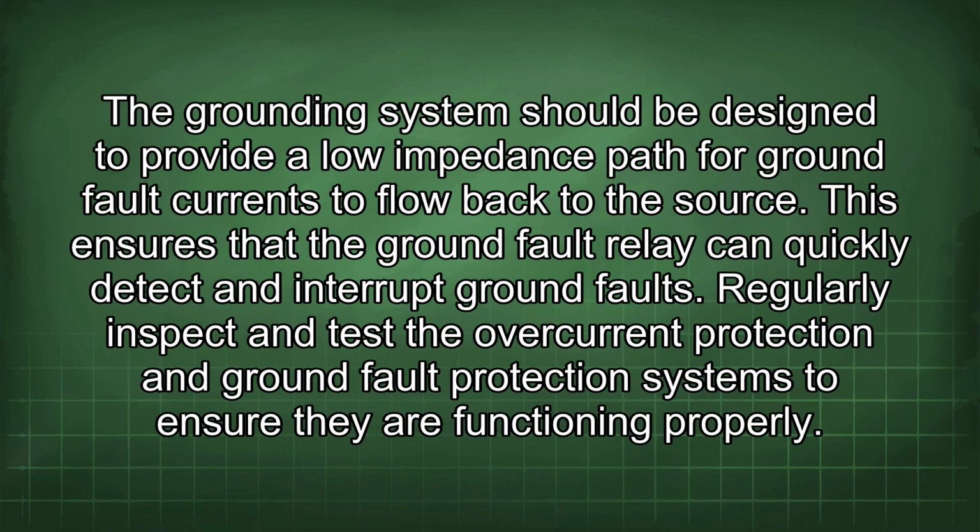Proper grounding is essential for effective ground fault protection. The grounding system should be designed to provide a low impedance path for ground fault currents to flow back to the source. This ensures that the ground fault relay can quickly detect and interrupt ground faults.